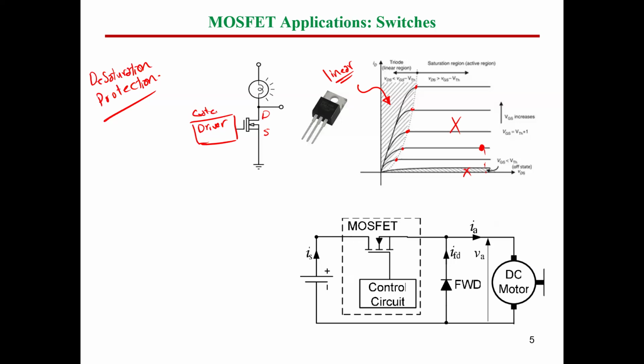The gate driver will have isolation. Isolation means the ground of this side, this is ground, let's say power ground P, and this is signal ground S. So two different grounds. And in between, we have what's called galvanic isolation. This galvanic isolation, guys, can be in several kilovolts. So it can be 2 kilovolts, it can be up to 5 kilovolts, for instance, in most drivers.